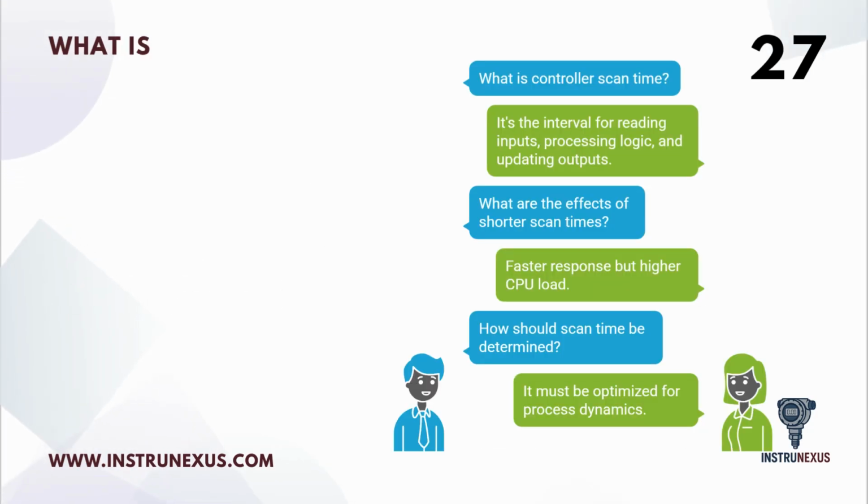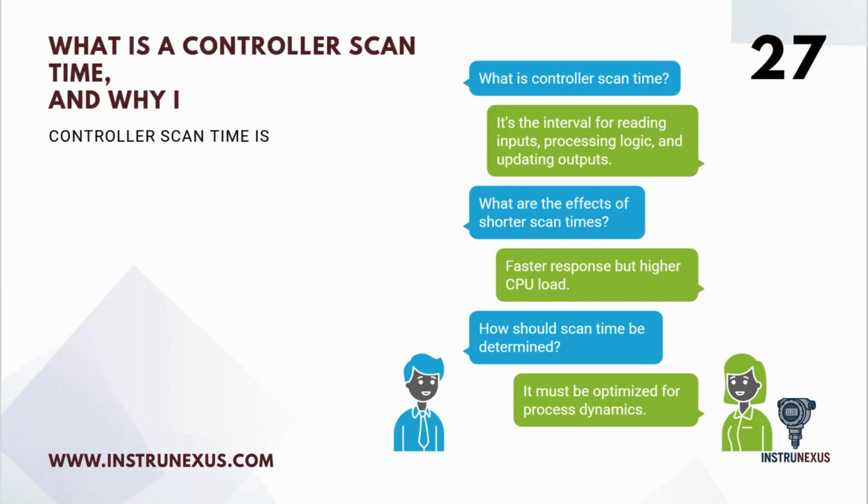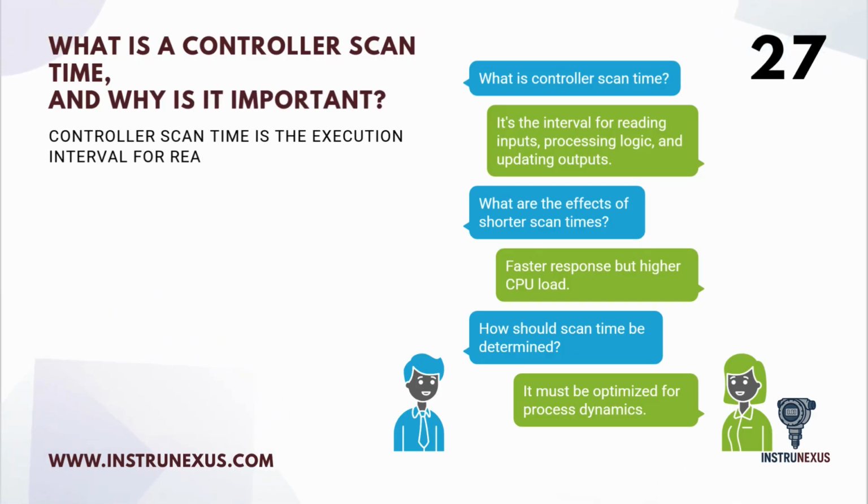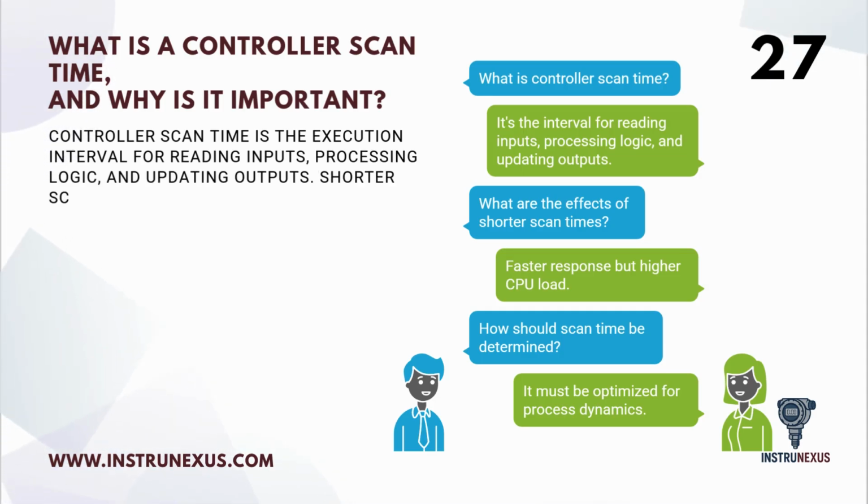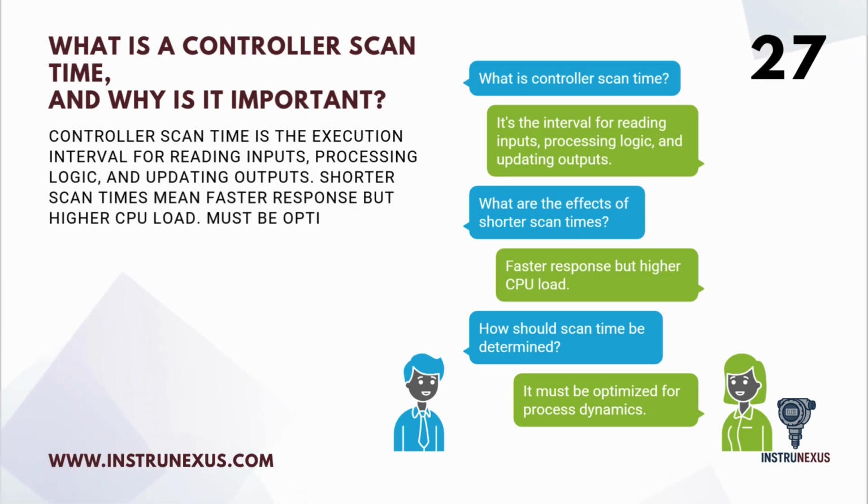What is a controller scan time, and why is it important? Controller scan time is the execution interval for reading inputs, processing logic, and updating outputs. Shorter scan times mean faster response but higher CPU load. Must be optimized for process dynamics.